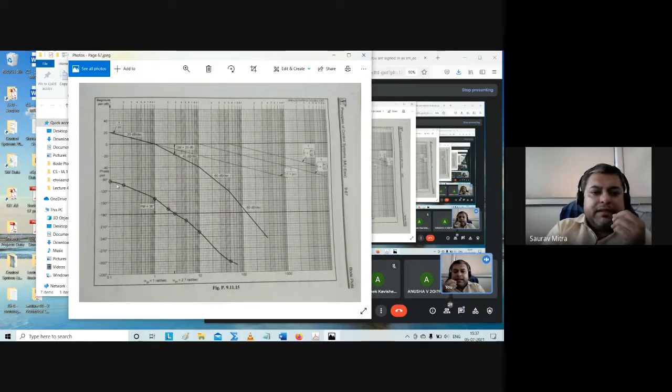Okay, and below is actually the phase graph, and the phase graph does not need any k value because k value is constant. Okay, so k value is constant means you are finding that now gain crossover is happening at somewhere here, and at gain crossover you are finding that phase is around 36 degree above 180. So in this point, that is gain crossover, which is around 1, you're finding that the phase is around minus 144 degree, I'm sorry, it is minus 144 degree.